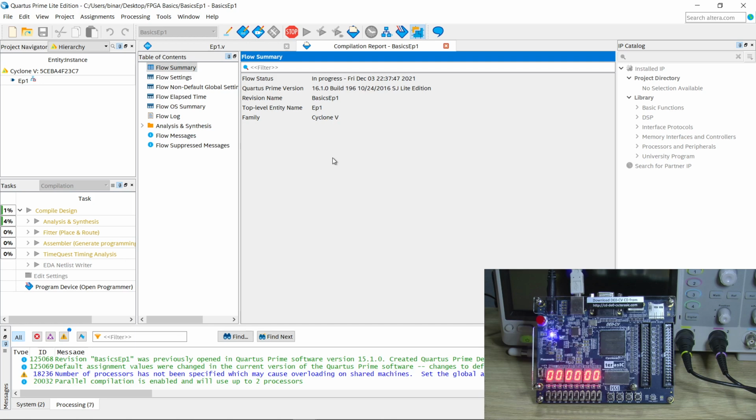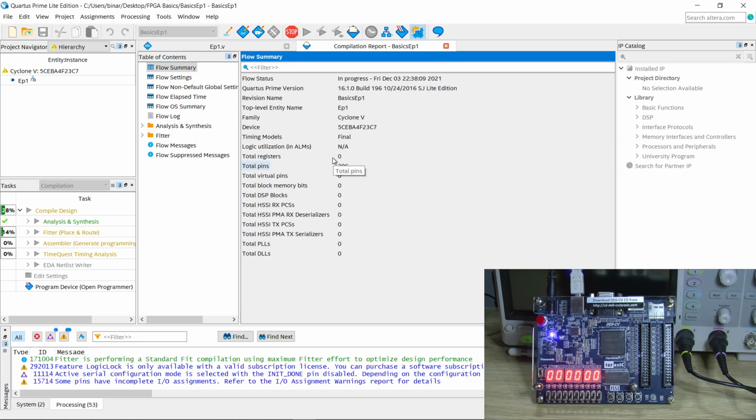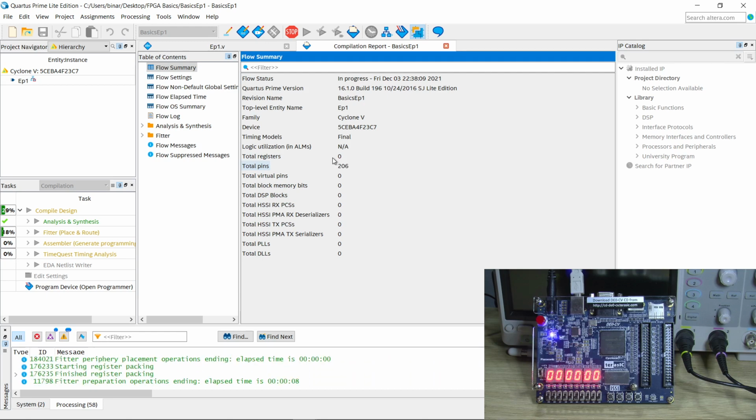Now, we'll have a look at how this works, and then we're going to try something a little bit more complex, which is also going to allow us to see what it does as far as our chip planner, as well as seeing how it will actually show us the actual circuit diagram of what it is setting up in the FPGA for us based on our Verilog HDL code. Now, if you've got a really complex project, it can take longer to compile. That is part of it, because it is a bit of a complex thing that it's got to go through and do.